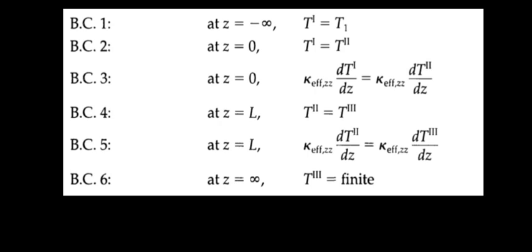And now boundary condition 6, at the outlet of zone 3, that is z tending to positive infinity: the temperature gradient approaches 0. Similar to the inlet condition, the assumption of an infinitely long exit zone is a mathematical simplification. This condition implies that far downstream from the reaction zone, the temperature profile becomes flat, indicating that there is no further net heat transfer in the axial direction. This often occurs when the fluid has reached thermal equilibrium with its surroundings or when axial conduction becomes negligible compared to the bulk flow of heat. This is a type of zero gradient boundary condition.